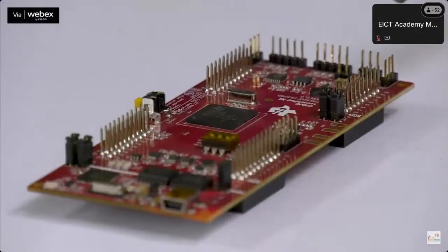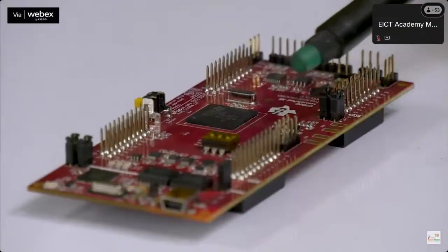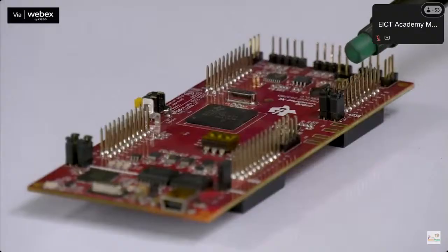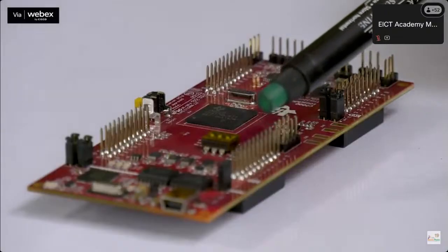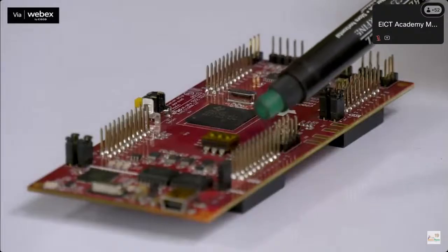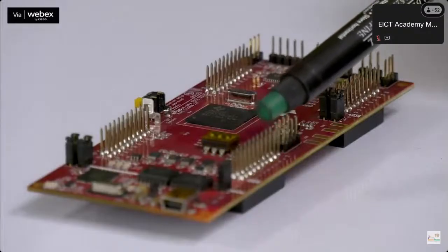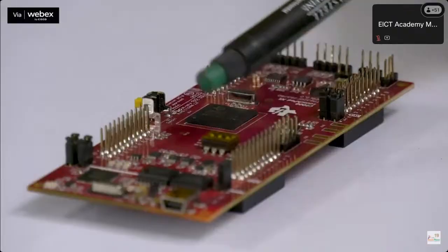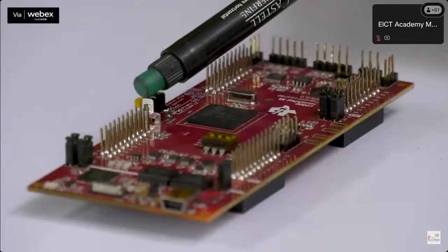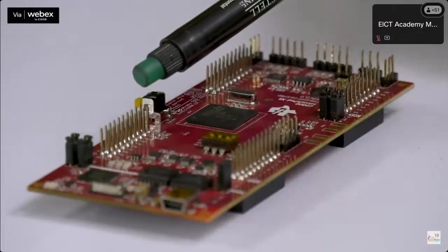For developing any rapid control prototyping, we need to configure the analog to digital converter (ADC) and PWM pins of the DSP controller. Generally, the DSP controller has 16 ADC pins of 0 to 3.3 volt input range with 12-bit resolution. It has 12 direct PWM pins for generating PWM signals at desired frequencies.